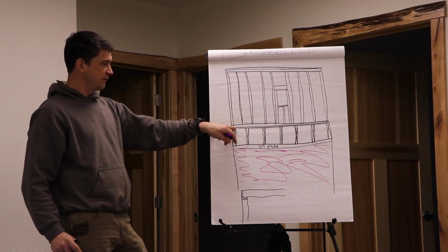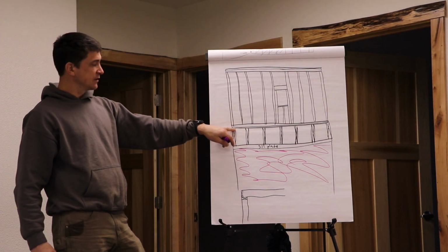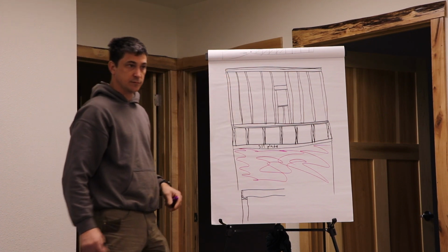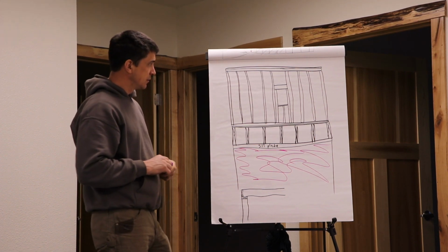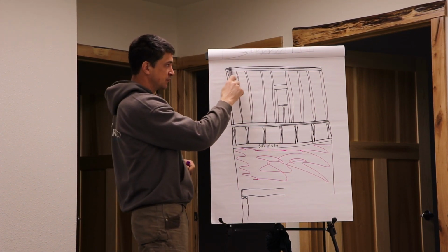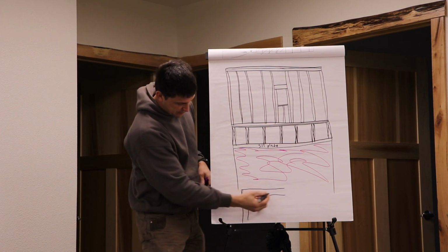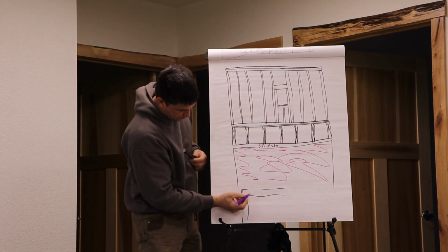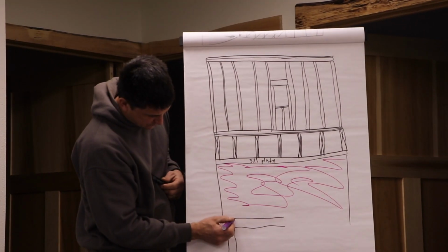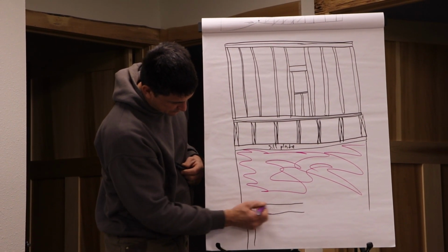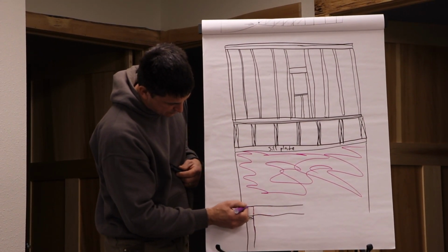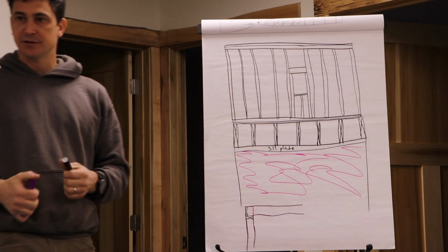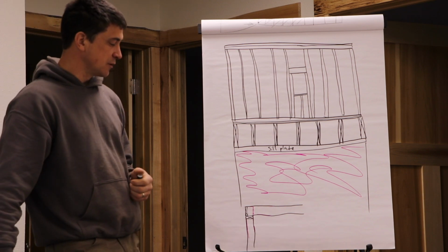On the bottom we have it all fastened to this sheathing, so that ties the bottom together, but how are we going to tie this top together? Use the top board to fasten each other together. Yep. So the first option is we've got this double top plate. Our first one ties together like this. Then the second one, the double top one, we end the one going this way right across here, so it runs that way. And then this one runs out there. They overlap at the corners, nail it all together, and it's super strong.